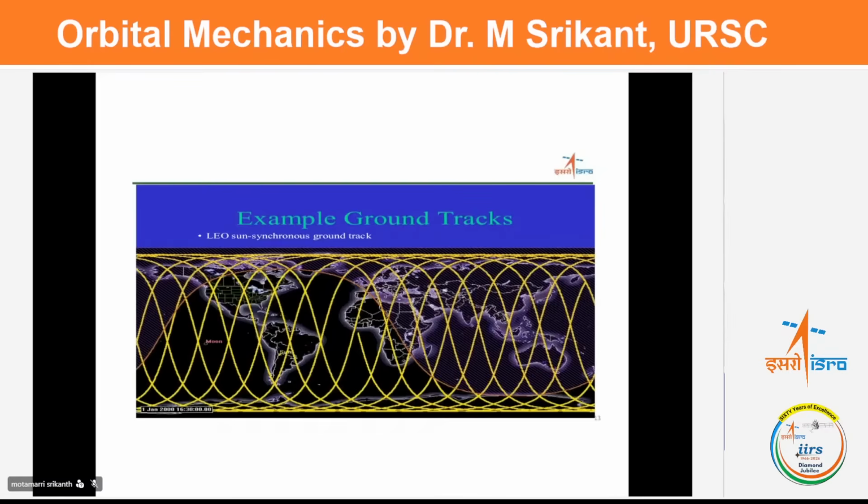If somebody asks me to cover the globe within 2 days, how is it calculated? We know that the Earth's circumference, 2 pi r, is around 40,000 kilometers. If the swath of the payload is around 1440 kilometers, you can see that around 29 orbits are required approximately to cover the whole globe. This is at the equator. At higher latitudes, this improves significantly. At the equator we have to see the worst case for coverage.